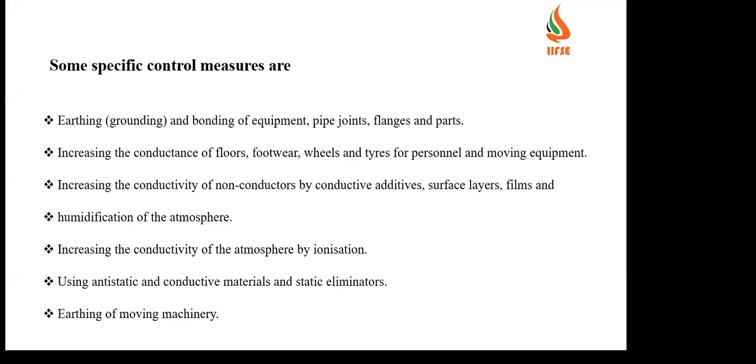If it is an insulator, non-conductive material, there will be some conductive additives, some coatings applied, or surfaces created, or a layer formed. By forming a conductive layer, we can control the accumulated static electricity. Humidification of atmosphere. So humidification: the more the atmosphere is dry, the more chance of static electricity. If you are making it humidified, with a higher percentage of water vapor in the air, less static electricity is generated.